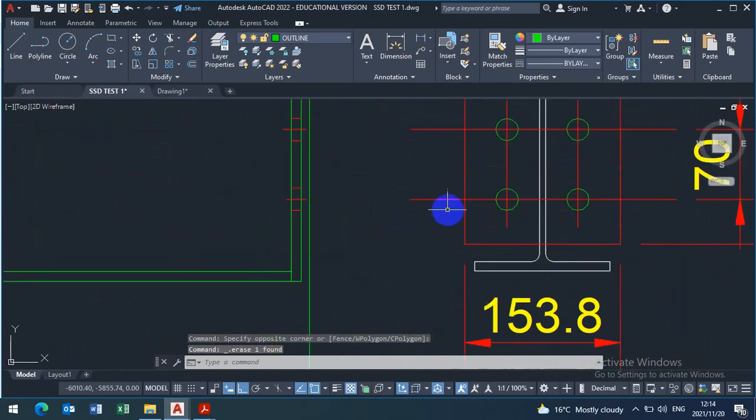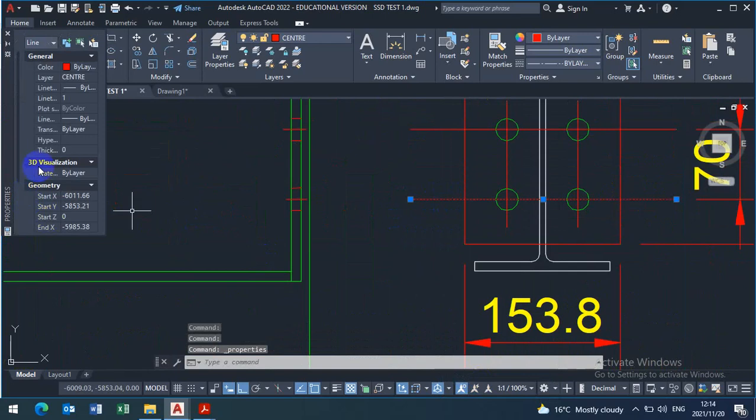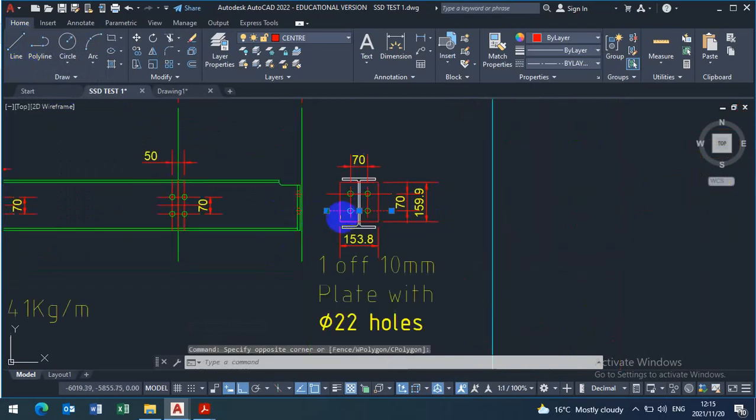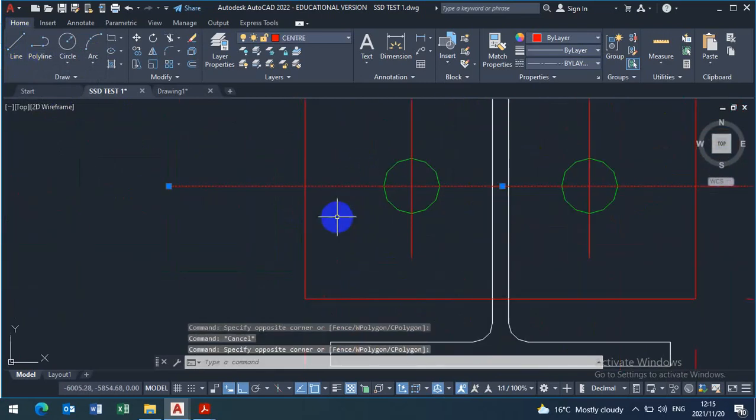And then if you can't see the centers, you select the line, right click, properties, then you increase the line scale, maybe 5, then press enter. If it's not 10, enter. I see it's still not showing. Try to go back to 1, enter. 0.5, enter.